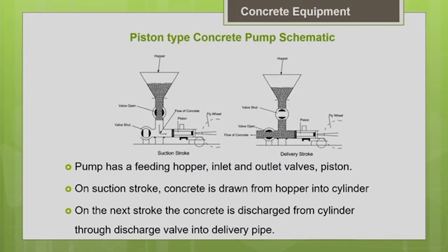So there are different types of pumps available. The most commonly adopted method is your piston type concrete pump, the reciprocating piston type concrete pump. This is a schematic picture of this piston type pump. Basically these pumps will have a hopper. This is a hopper, and into this hopper you have to discharge the concrete.